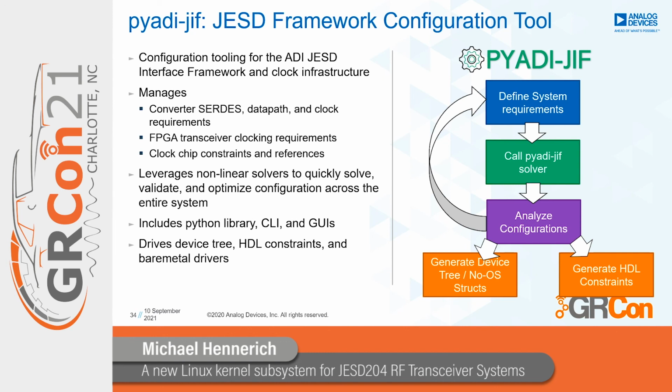The whole thing is you can use this configuration tool to actually validate application-specific configuration before you order an FPGA board or before you make some component selections on clock chips, VCXO frequencies, and so forth, as it will definitely tell you whether you can use this FPGA in this speed grade or whether you can use this VCXO frequency and so forth. So it's a great tool to validate things before you actually implement it.